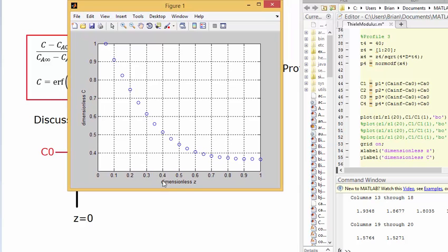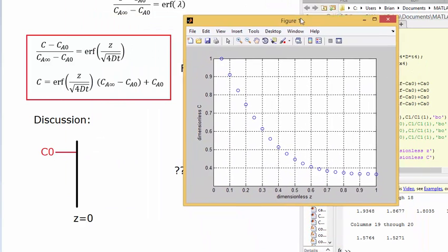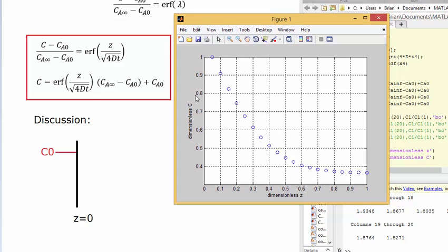So on the x-axis, you'll see dimensionless z, and on the y-axis, you'll see dimensionless concentration. So 1 just represents hitting the end of the infinite slab, and the axis on the left-hand side is the high concentration, on the right-hand side is low concentration. So as you get further and further along into the infinite slab, your concentration is going to drop. Okay, we get this sort of exponential looking profile here. These values were taken, the y values were taken using a normal distribution table to evaluate for the error function, which your professor should show you how to use if you're going to be doing some example problems on this.